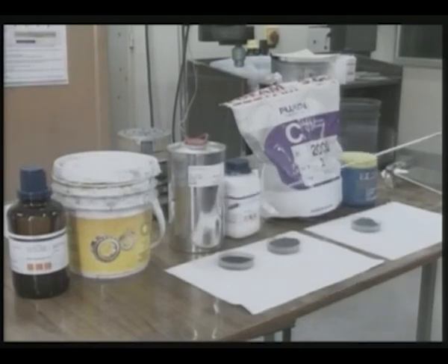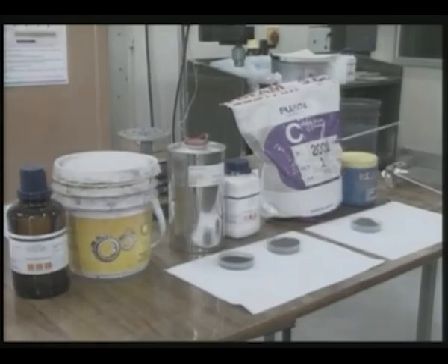Iron particles are of 2 types. It can be carbonyl iron particles or it can be electrolytic iron particles. People all over the world are using carbonyl iron particles, CIP particles. It is manufactured by BASF Germany, and this is the electrolytic iron particles. It has a bigger size, 250 to 300 mesh size. The third part of the magnetorheological polishing media is abrasive particles. Abrasive particles may be black silicon carbide or boron carbide, or aluminum also can be used.